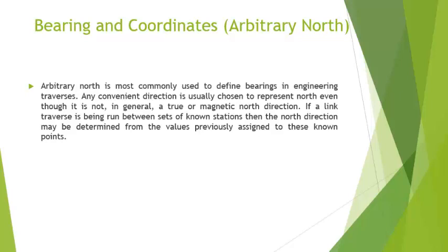So how about 45 degrees east? North 45 degrees east means 45 degrees in azimuth. Remember the clockwise rotation. The reading of bearing starts from the north or south to the east or west. If we apply this quadrant concept, then we definitely talk about bearing.